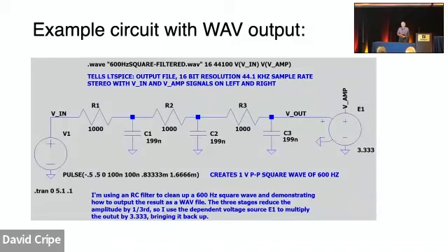So here's an example. I thought I would take a square wave over here on the source. That's a 600 hertz square wave, 1 volt peak to peak. By the way, this thing wants no greater than 1 volt, so watch that. I've gone archaic here. I've got RC filtering, 3 stages of RC filter to try to make that raspy sounding square wave into something approaching a sine wave. And by the way, it reduced the amplitude by 1/3. So a little bonus thing for you.